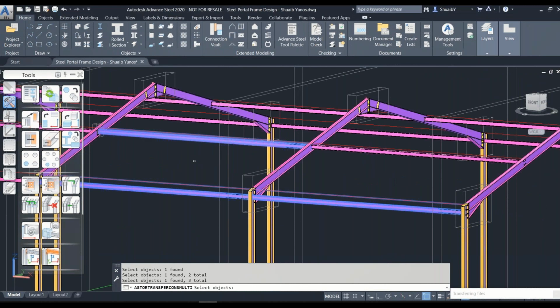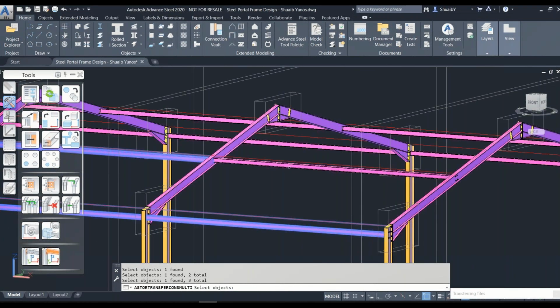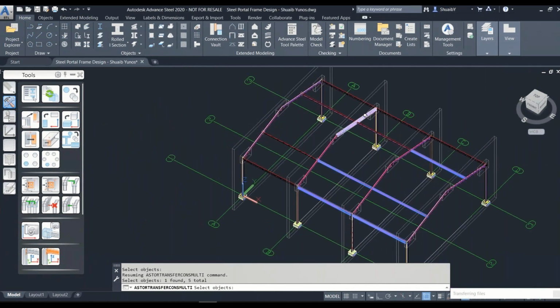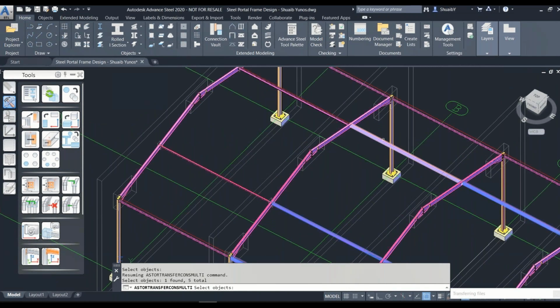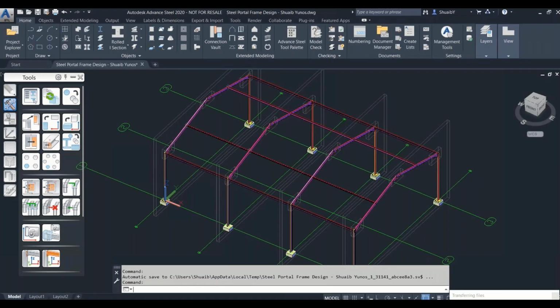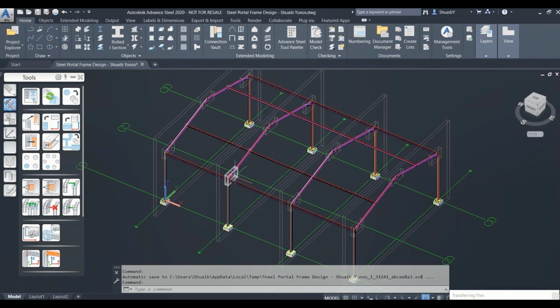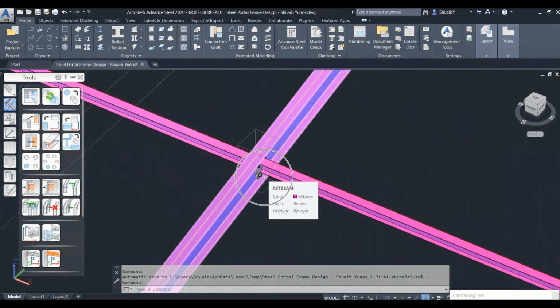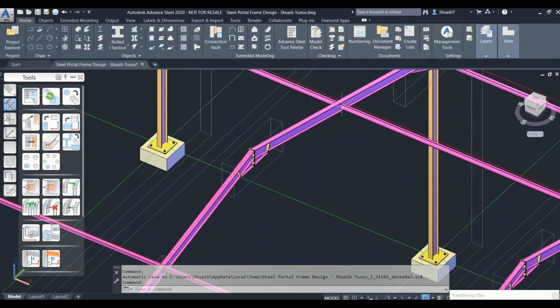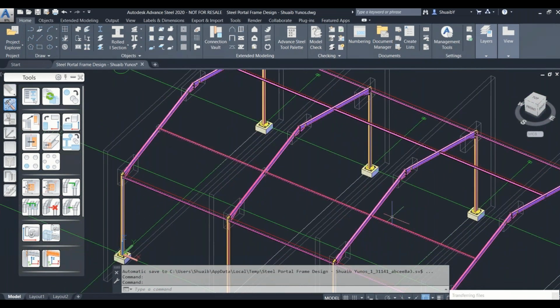So let's go and select the members that will be affected or need the double-ended or double-sided plate to be connected. So it will be those. Okay, and of course it's going to be connected to that, right? So people normally get confused at this stage, so I've done it here. So I've identified what we want. So we want to use that connection. We were going to assign it to the other elements that need that same detail. Okay, and it's going to be connected to those elements.